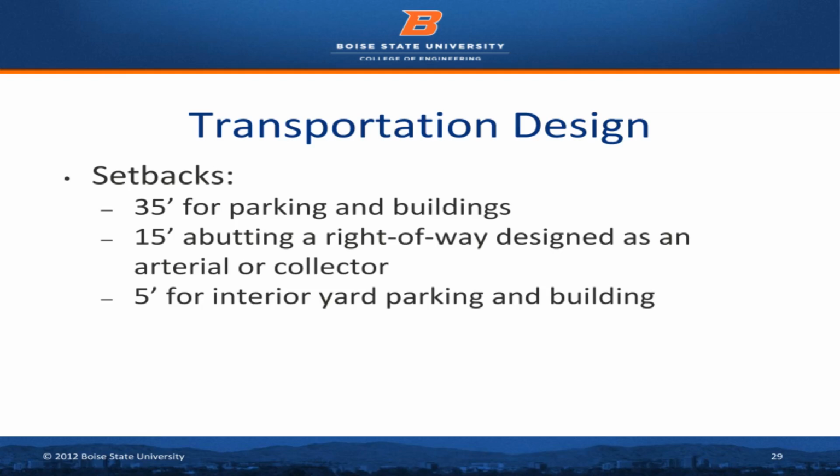For the setbacks, the NAPA Transportation Manual states the setbacks that are required for the parking lot and also building must be at least 35 feet. There also must be 15 feet abutting a right-of-way designated as an arterial or collector. In addition, the city requires 5 feet setbacks for the interior yard, parking, and buildings.